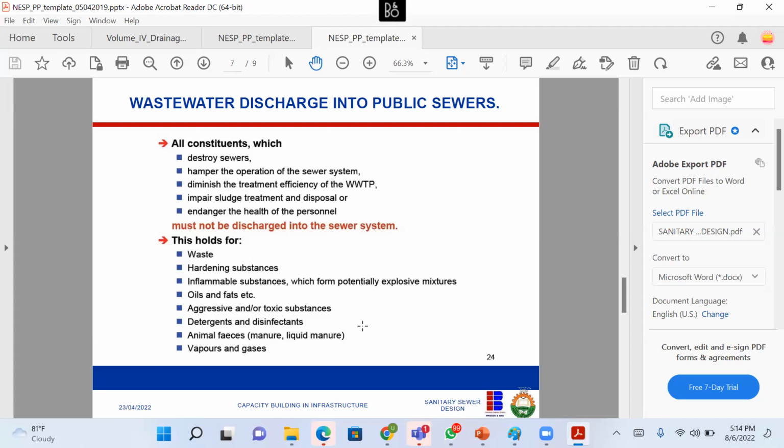It is dangerous to discharge chemicals into the wastewater treatment system. Please don't do it. If you do, there's a possibility that it might get to the wastewater treatment plant and kill all the bacteria that they have built over the years. Wastewater is treated by getting a number of bacteria, putting them together, and they start to feed on the wastewater that is already rich in organic content, right? So somebody has been culturing bacteria over the years, and then suddenly you discharge something inside, and the whole thing will start from scratch again. In developed countries, I'm telling you, you'll be jailed if not prosecuted.